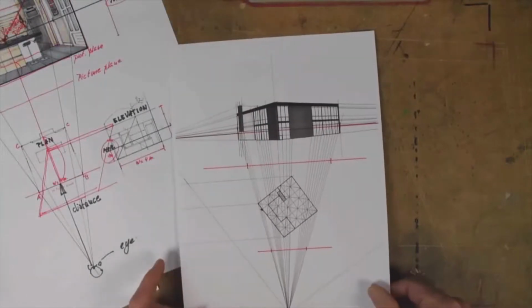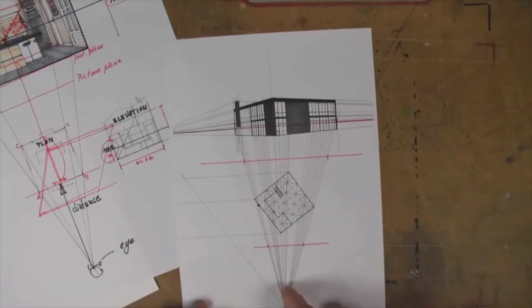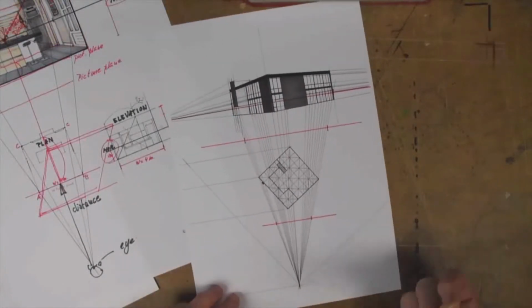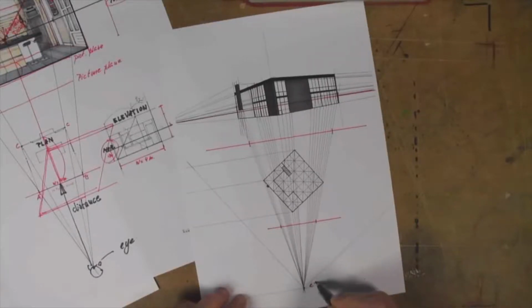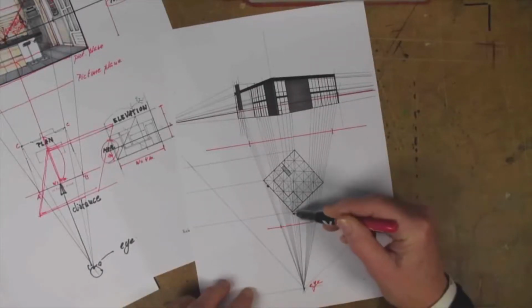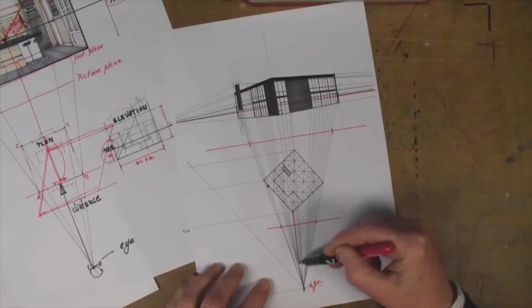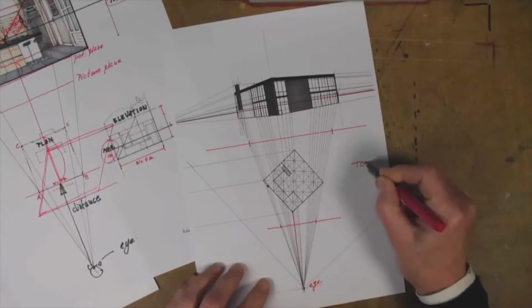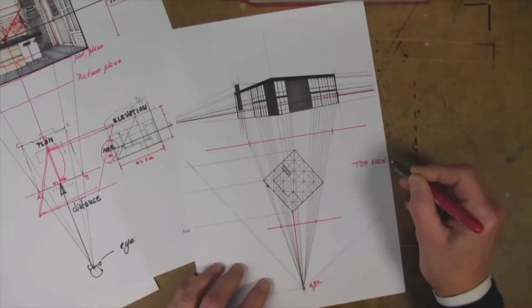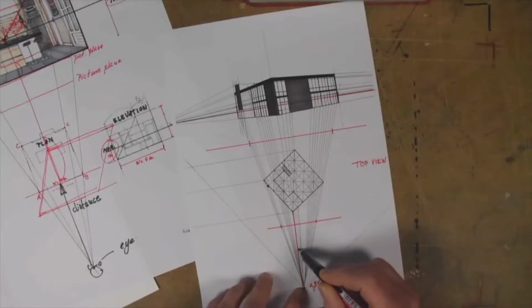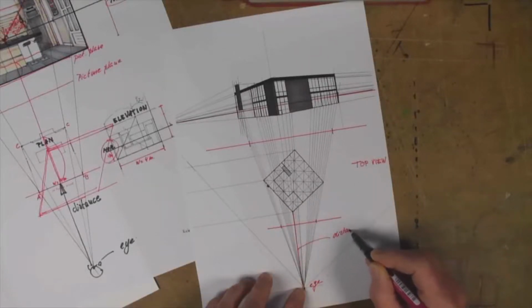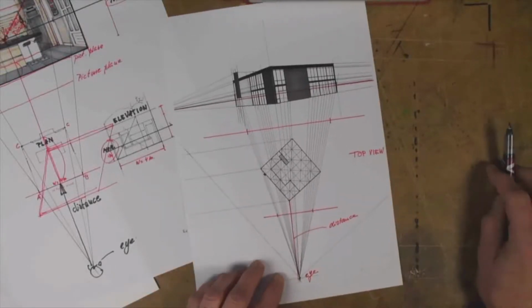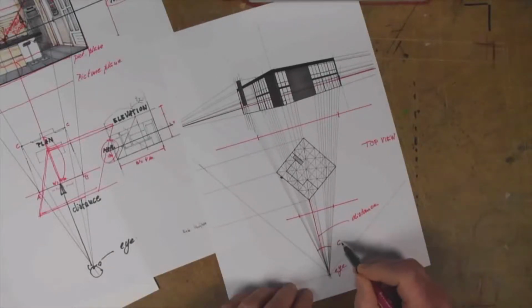If you want a two-point perspective, you have to position the plan differently towards the observer. I turn the plan or square in the wanted position and choose the point from where you want to observe the object. This situation is as seen in top view. To make a correct, undistorted perspective, your distance should be so far from the object that the cone or angle of vision isn't bigger than 30 degrees.